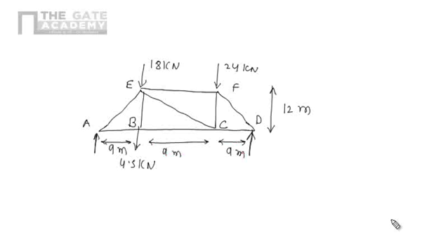So again I draw the truss diagram, and now we are interested in the member FC. By method of section, we have to cut the section so that it passes through 3 or fewer members. If we cut the section like that, then we can easily solve this problem. So now draw the free body diagram of a smaller part.